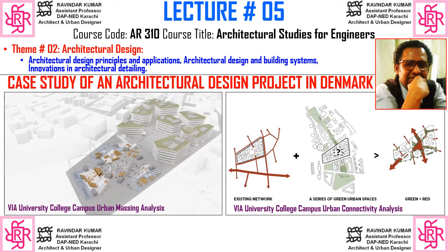Then there was a massing analysis: how big the building should be, what should be the height, what should be the overall form or mass of the building, and what is in the surrounding. The shape and geometry of the surrounding buildings is taken into consideration so that the design responds to the surroundings and does not affect them. For example, if you make a very high-rise building, it will cast a large shadow, and the low-rise buildings will get affected, and their wind movement and light will be affected. That's why the architect has to be very careful when he thinks about the building mass.